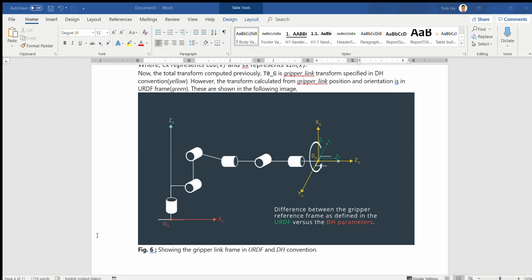You fill in any value from theta 1 to theta 6, and it creates the position for you. For example, 0, 0, and you run it. Okay, in the homogeneous transformation matrix, you have to know the first column, second column, and third column, and this matrix is really important.